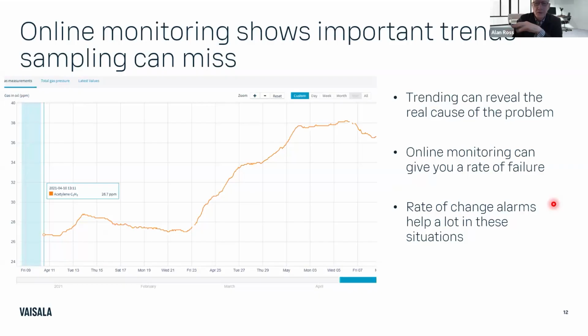Okay. I think this also answers what you just said, and Lee, do you have anything to add to that? The only thing I would add is that there are many levels of sophistication that you can get into these days when it comes to data interpretation. It can start with Duval triangles, you can look at trend analysis, and then there are even more sophisticated tools out there as well.